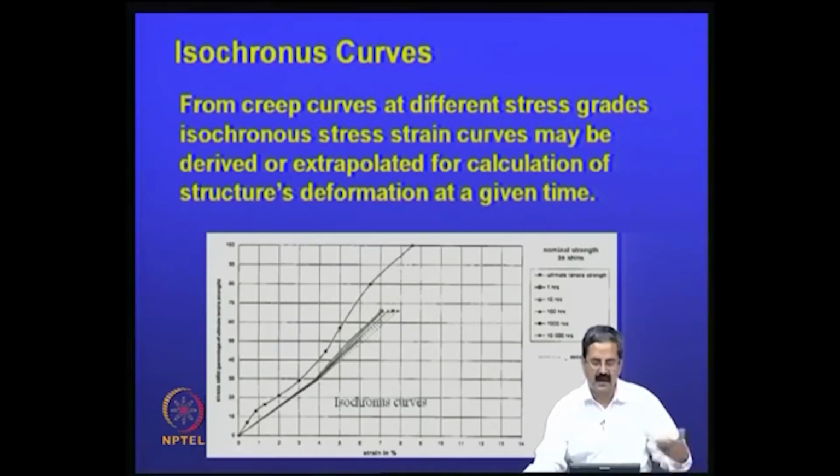So for example, if the tensile strength could be 35 kilonewton per meter, and you want it to work for about, say, 50 years, you may have to use a creep factor of 1.3 or 1.5 or whatever. So it depends on this type of testing. Okay.